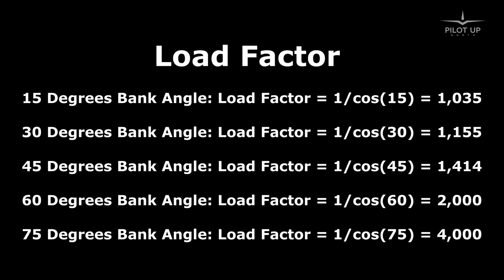Here are the load factor calculations for bank angles of 15, 30, 45, 60, and 75 degrees. 15 degrees bank, we have 1.03. 30 degrees bank, load factor 1.15. 45 degrees bank, load factor is 1.41. And look at this, 60 degrees bank, load factor is 2.0 Gs. It means double of your weight. If you are 80 kilos, in a turn of 60 degrees, you will experience a weight of 160 kilos.